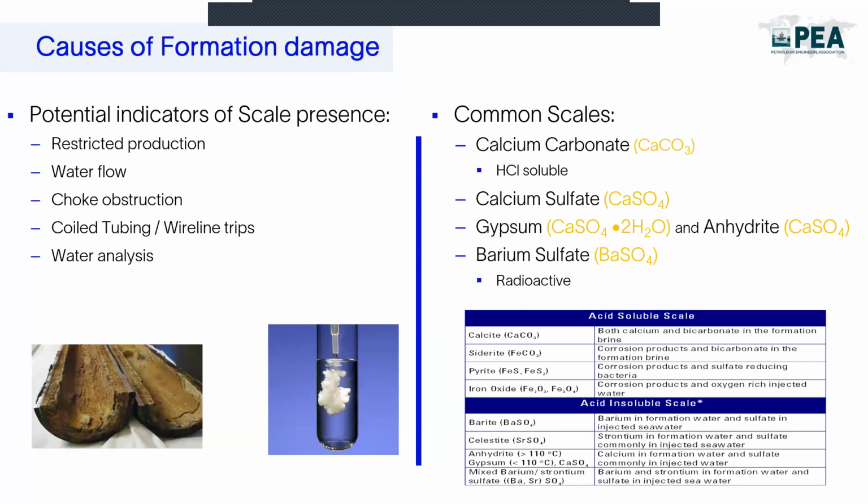The change in temperature, the change in pressure, the change in pH, all these different types of water being injected into the reservoir create interactions or chemical reactions that lead to the deposit or buildup of scale either in the wellbore or in the reservoir. And of course, when it happens in the wellbore, more or less we can manage it. But if it happens inside the reservoir, it's going to be a serious issue.